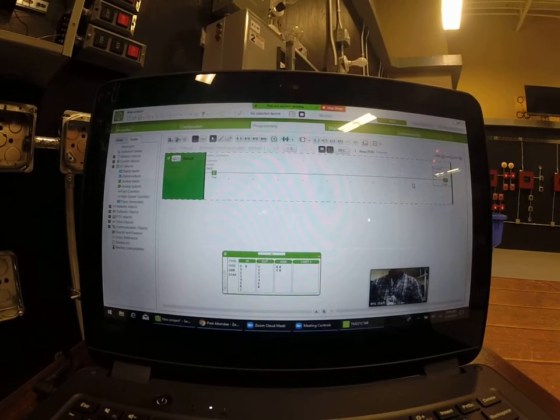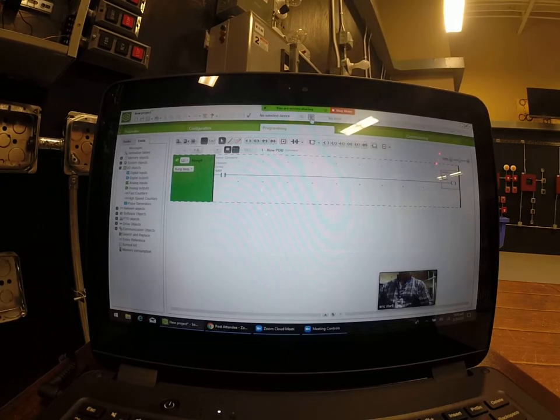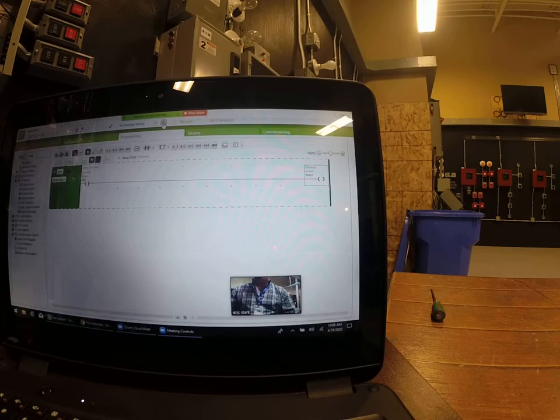Now we're going to show you how to transfer this program over to the controller. So we'll unclick this, and you can see the contacts went back to their normal position, nothing's energized. We're going to go up to the top of the screen where the launch simulator was, and we're going to stop the simulator. We'll lose that bottom drop down screen. Once that simulator stops, we're going to go over to an icon that's called commission. We want to transfer this program.